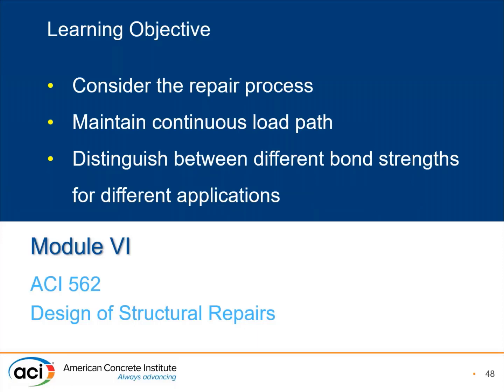So the learning objective for this module, as we switch gears from the assessment and rounding out what was started in part 2, is to consider the repair process. There are a variety of different repair techniques and technologies, from conventional to post-tension to FRP, et cetera, that should be evaluated and considered when looking to repair a structure.